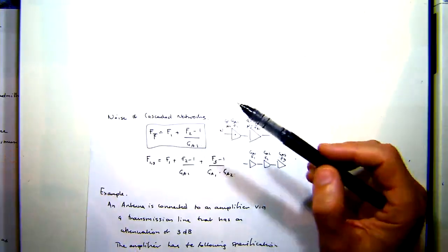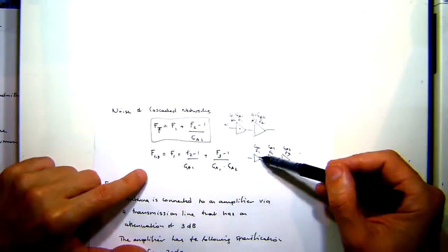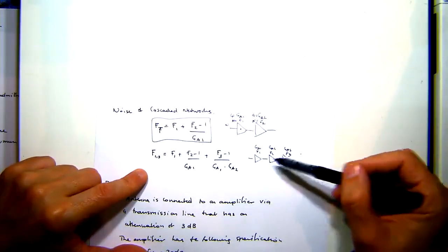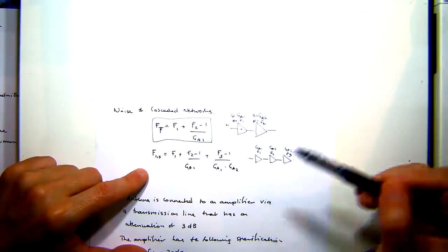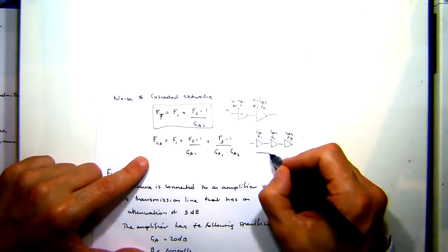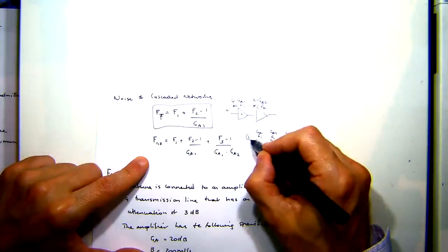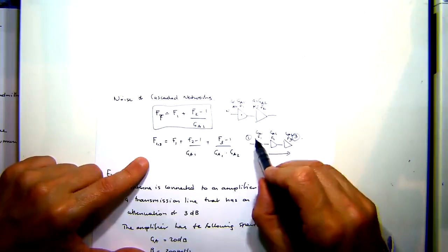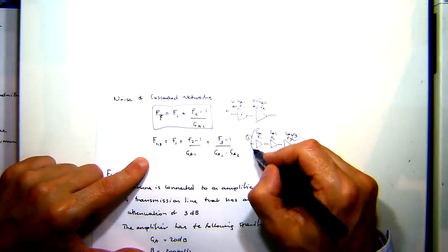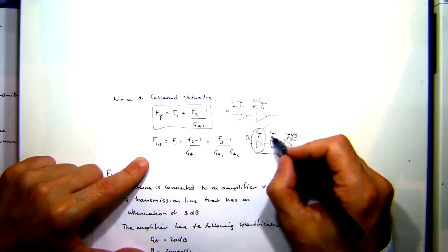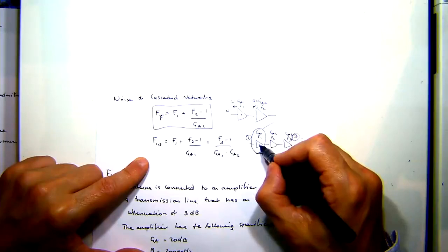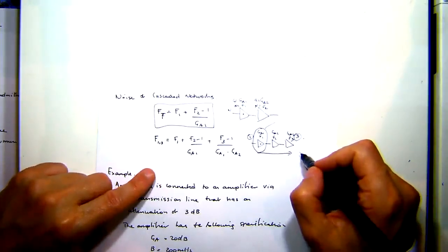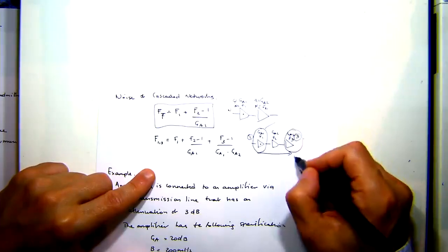Okay? And what I'm showing here is as you're moving back or forward, this is why there's always this confusion. If this is the first and this is the third amplifier, in this particular case, provided the other gains are high, this amplifier has the highest contribution. Which amplifier has the highest contribution to IP3? Well, the IP3 is the last one. The last one, okay.